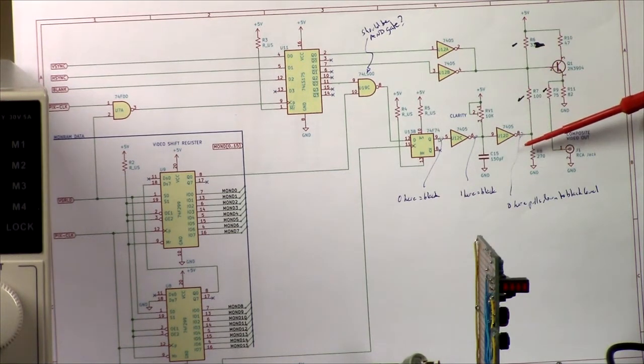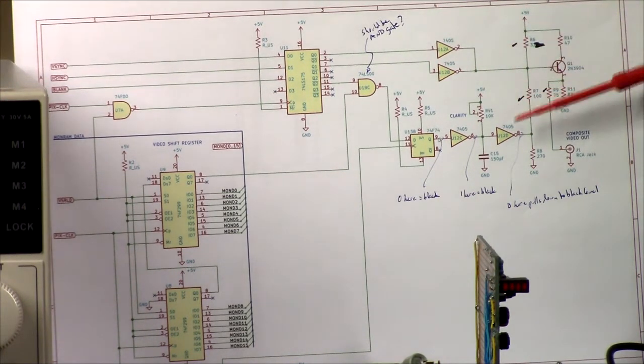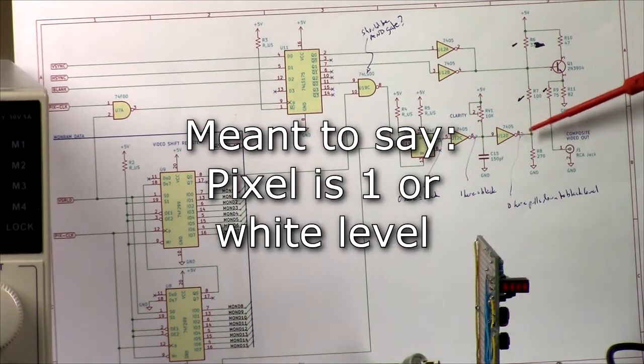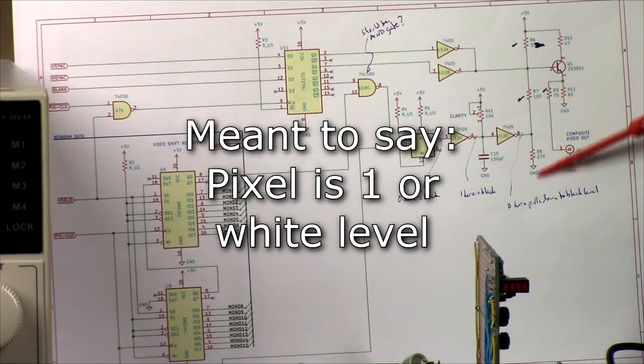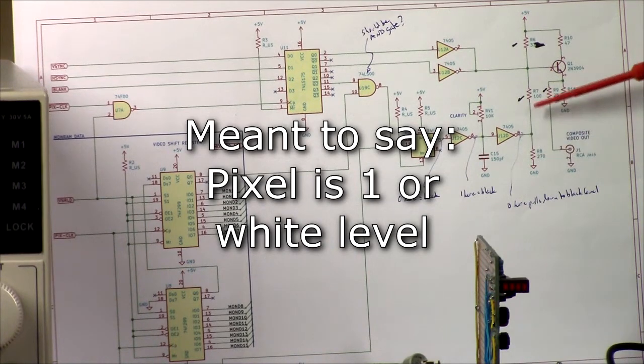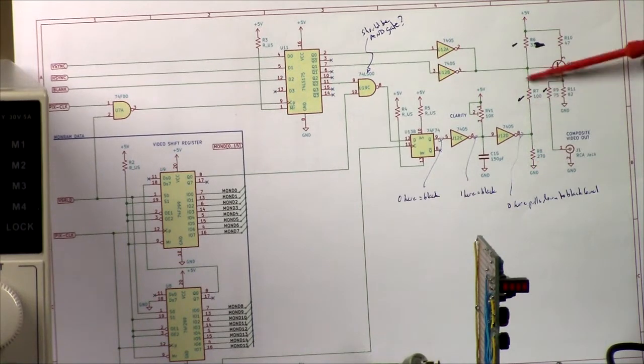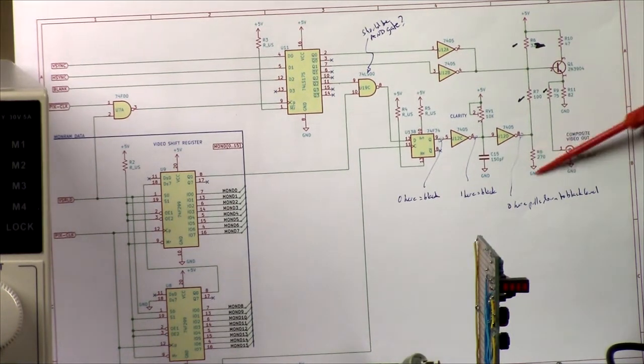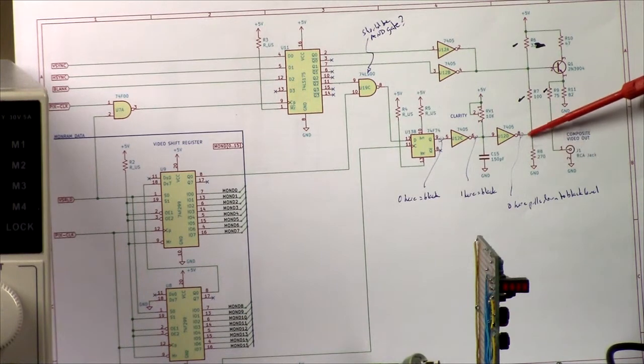And when they're all off, that is, there's no sync pulse and the pixel value is 0 or black level, then this extra resistor is added into the mix, and so we get a different value here. So switching this resistor in or out is how we switch between black and white, or whatever that was, 0.3 volts and 1 volt.